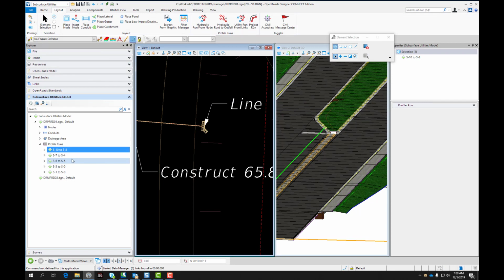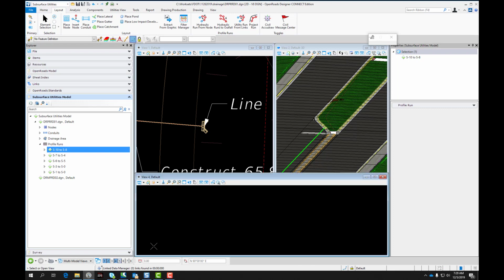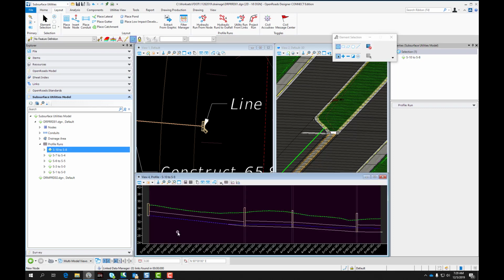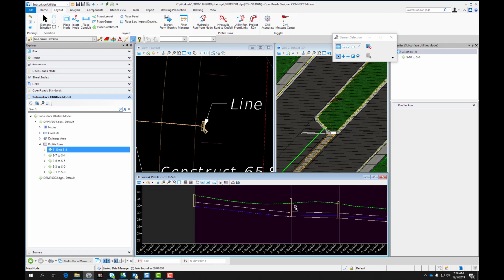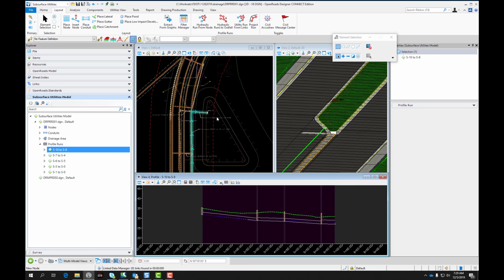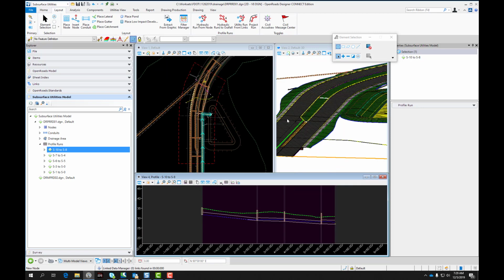The other profile is an actual CAD profile. So if I right click and choose open profile model, it's going to ask me to select a view. So if I choose view 4, now I can see the actual profile as it goes through CAD. Now the other thing about this profile is if you want to see the rest of what's along the trunk line in the model, so in other words, if I wanted to see where the roadway plots, not just the existing ground, there is this tool here which is create 3D cut.